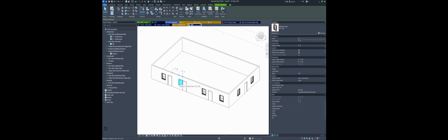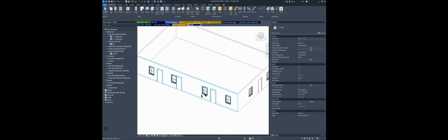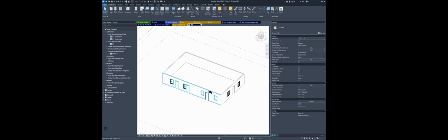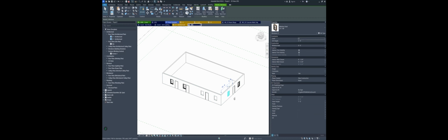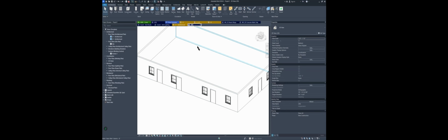View template group. Because this is something common. You guys will use Revit to do stuff during the semester, and you might have some reason why you want to isolate something. I'm hoping after coming out of this presentation, you are not like, okay, let me select this window and this window, and let me right click and hide in view, and then you go to the next floor and select again. No, coming out of this presentation, you know that you can just create a view template.